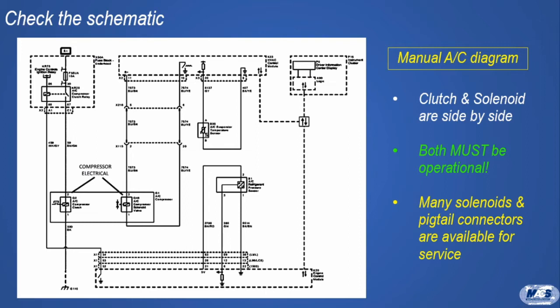Obviously, that's not so. Without the original parts, we can't tell if the compressor failure was only in the solenoid or a connector that had come off. If the connector was off and out of sight, that could explain why the technician might have seen only a single connection at the clutch. At one time, a compressor with a control valve might be clutchless, but no more.